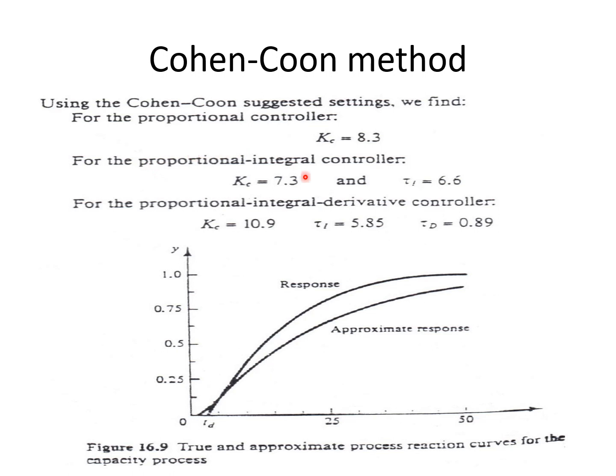If I use the PI controller, this is going to be Kc and tau I, depending on the formula you use. If you use PID, this is going to be Kc, tau I, and tau D. So you can see different Kc, different tau I, tau D when you use different types of controller and different systems. So there are no specific standard controller settings for different types of controllers and so on. So this is an example of using the Cohen-Coon method. These are the controller settings you are going to get.